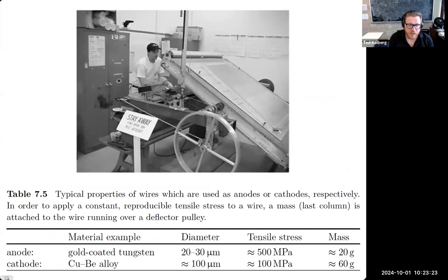The way that you typically manufacture this chamber is by winding. So imagine a simple geometry like the one we had on the previous slide, where you have one layer of wires, which is spread across a plane sandwiched in between two cathode plates. It turns out that there's a convenient way to manufacture this thing by taking one long wire and winding it around the chamber.